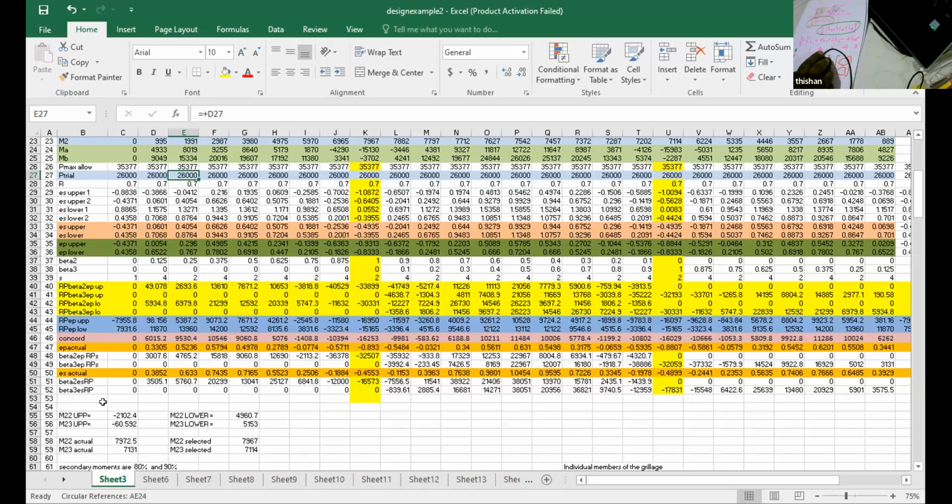On the other hand, if you select an inadequate pre-stressing force, there's no answer, and you keep on trying. When you bring the bending moment diagram into limits in one region, it will violate in the other region. So you will be just struggling a lot with SAP 2000 and this spreadsheet, because you are trying to find an answer that does not exist.